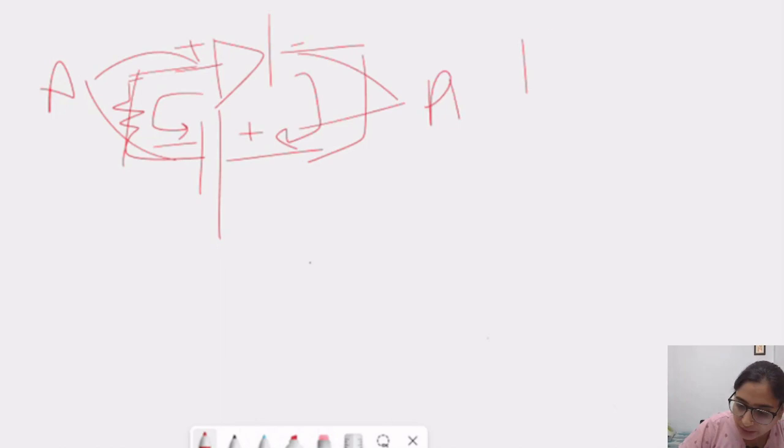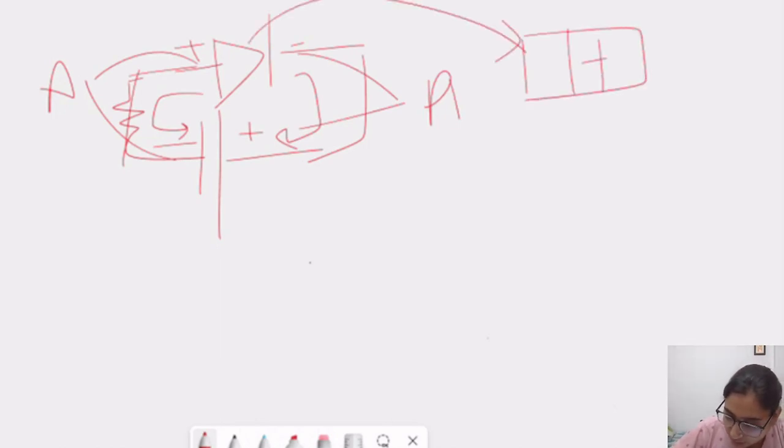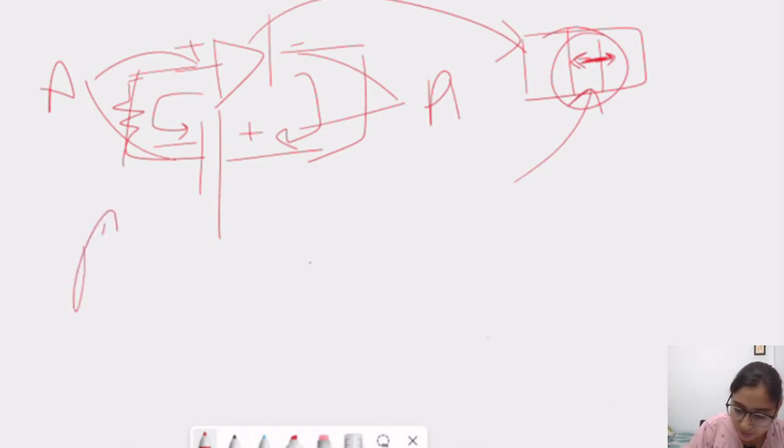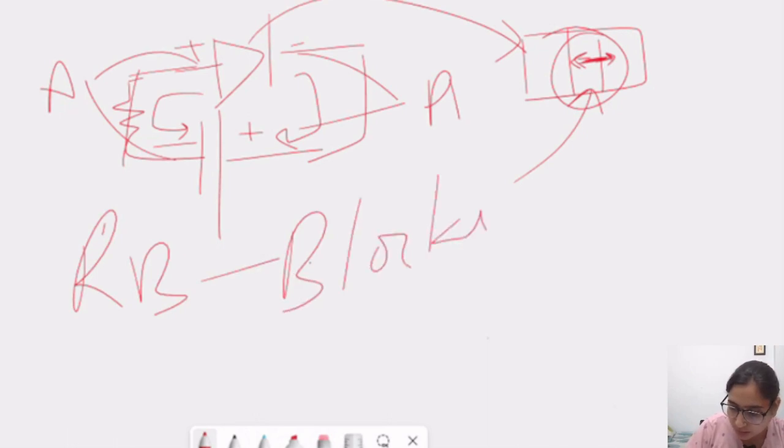So the depletion region of this PN junction will increase or become wide. And if this becomes wide, then it needs a very high voltage to rupture or break the covalent bonds inside this layer and start conduction. So this reverse bias condition is also considered as blocking bias, because it is blocking the current from flowing.